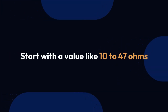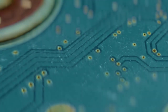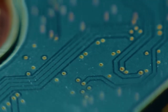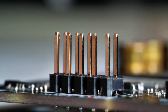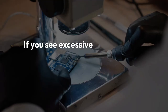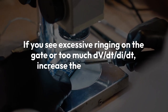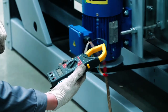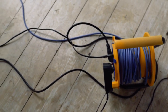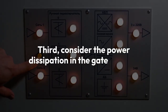A common approach is to start with a value like 10 to 47 ohms and then fine-tune it. Observe the gate voltage waveform, the drain-source voltage, VDS, or collector-emitter voltage, VCE, waveform, and the drain or collector current, ID or IC, waveform on an oscilloscope. If you see excessive ringing on the gate or too much dV/dt or dI/dt, increase the gate resistor. If your power losses are too high due to slow switching, decrease the resistor, but always stay above your R_G_min to protect the driver.